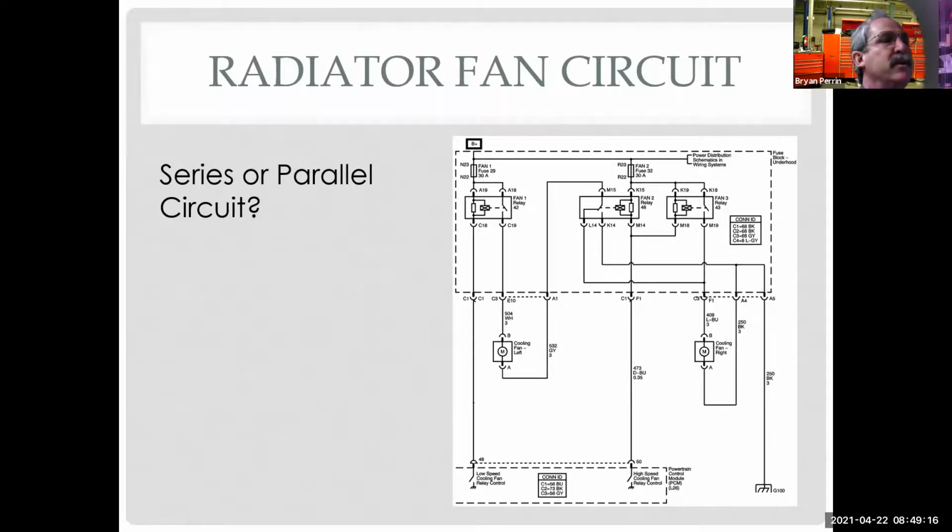So you can see where starting at the load makes sense, because if I just started at power, if I tried to start here, I got power going to both of these. Both these are relays. Okay, so I close this relay, it powers up this fan. Got it. What does this one do? Well, this one also goes to this. So you can see there's not one place that you have to start. But if you get to a spot that you're confused at, go to another place.